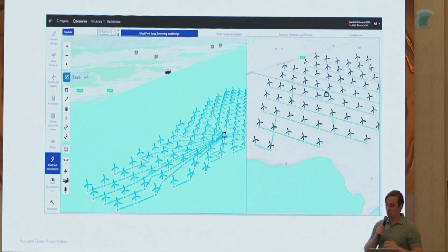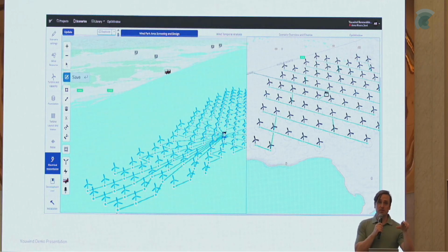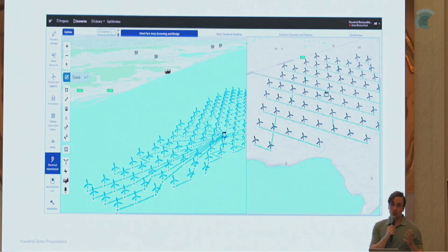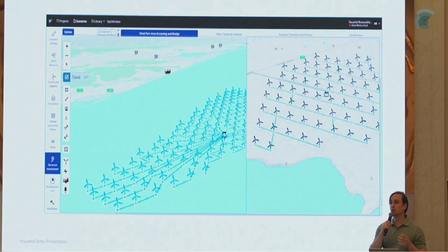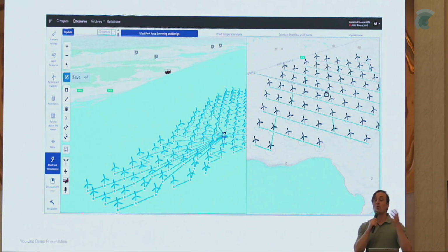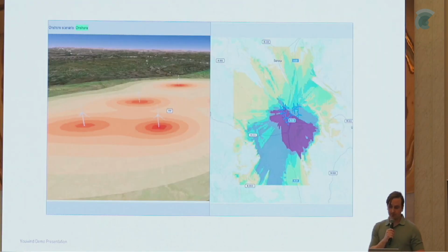But then we need to go into what we call this LCOE optimization, which is also making sure that the cables are connected with the shortest distance, and we evaluate what is the cost of energy when we're looking at what is the exact given scope of my electrical setup. Should it be offshore substations? Should it be 2 offshore substations? Which sort of cable should I add? What sort of cross section should there be, etc.